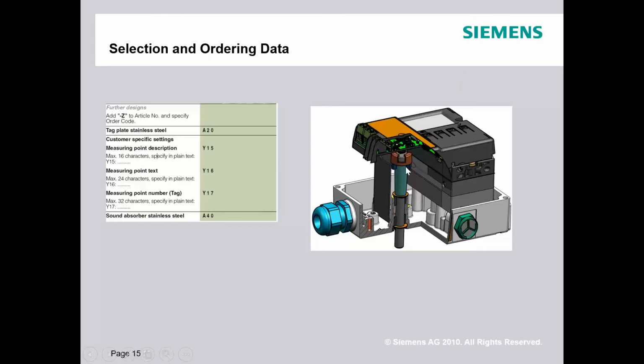This is a non-contact sensor. In our flagship product, it started life being a potentiometer, and we also offer this as an option in that product. All of these are magnetic non-contact. Now, so what? People say, well, is that good or bad? What do I get with that? What you get with that is, a potentiometer, God bless potentiometers, but where you have a problem is it's a mechanical wiper device, right?